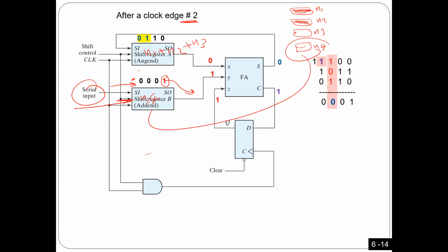Okay. Also, what I'm explaining here is that if I have an operation like addition, I can do it in two different ways. If you go to chapter 4, I did it in parallel. Here I'm doing it in serial. So here you add bit by bit. The good thing about serial is that I need only one flip-flop, only one. Even if I'm adding 1 billion bits to 1 billion bits, it's still one flip-flop. Very interesting. So it's good for hardware.